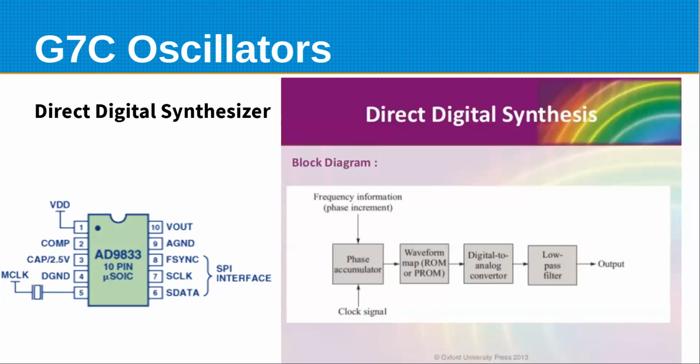And then I feed it through a digital to analog converter. So I'm basically converting those digital samples back into a sine wave and putting a low pass filter to get rid of all the high frequency stuff. So I've got a sine wave on the output that was done by just a lookup table essentially in that ROM.